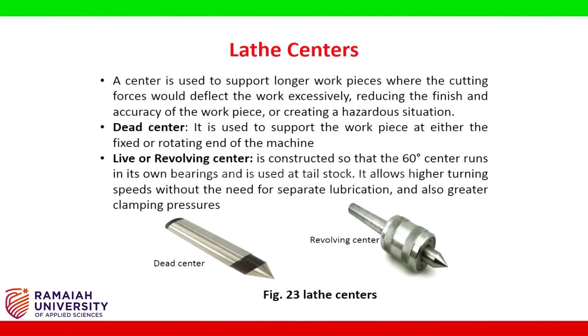Lathe centers. A center is used to support longer work pieces where the cutting forces would deflect the work excessively, reducing the finish and accuracy of the workpiece or creating a hazardous situation. Dead center. It is used to support the workpiece at either the fixed or rotating end of the machine. Live or revolving center. It is constructed so that the 60-degree center runs in its own bearings and is used at tailstock. It allows higher turning speeds without the need for separate lubrication and also greater clamping pressures.